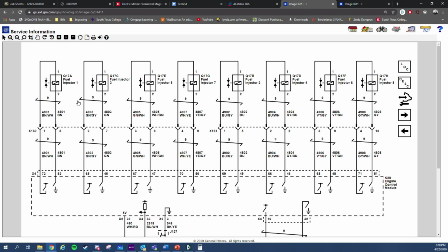Now these new engines actually have V8, V6, V4 modes, so they can run on 8 cylinders, 6 cylinders, 4 cylinders. Actually, Chevy has a system called dynamic fuel management where it can run on 1 cylinder. But it's able to alternate that cylinder to keep balance of the engine, alternating the injector from 7 to 1 to 6 to 8, whatever it needs to be. The way it's accomplished is your ECM can now drive both power and ground through 2 circuits to command an injector more precisely, depending on what is needed. Does that make sense? Pretty cool.